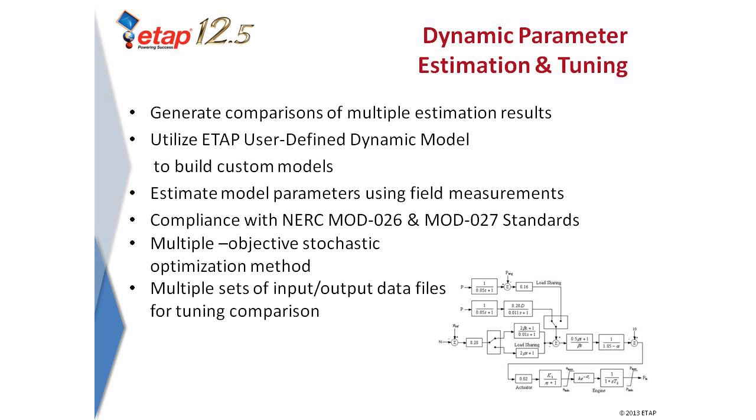In order to verify and validate the simulation studies, it is commonplace to compare simulation results against field test measurements, such as a generator load acceptance and rejection test. However, expertise is required to understand the effect of each parameter, as a simulation model is typically manually tuned to provide similar responses as the ones observed in the field test or recordings. The task of adjusting each variable via the trial and error approach simply is too tedious and time-consuming.